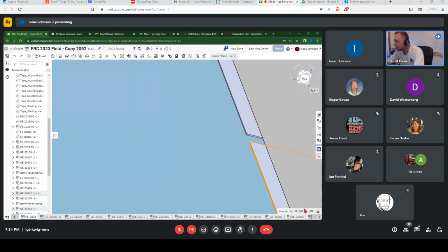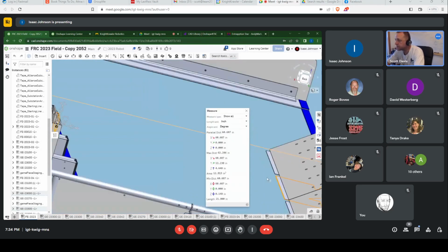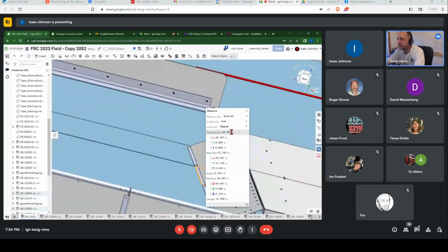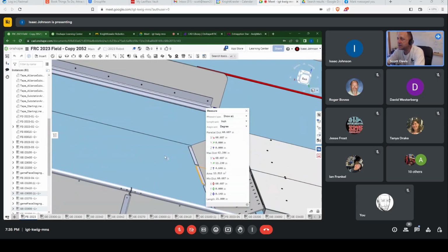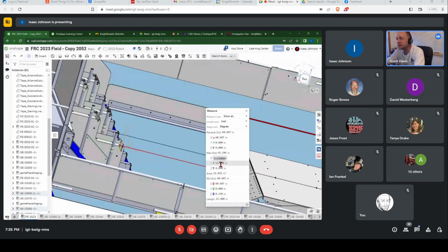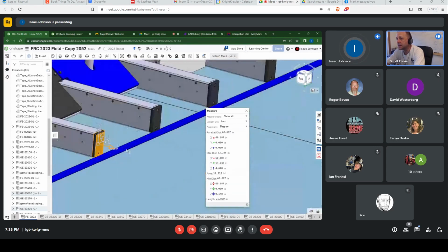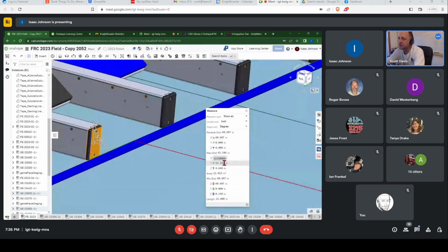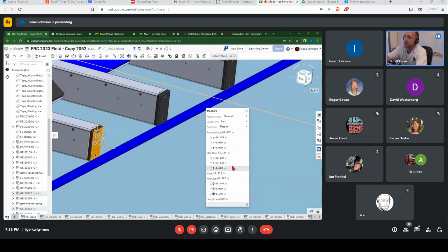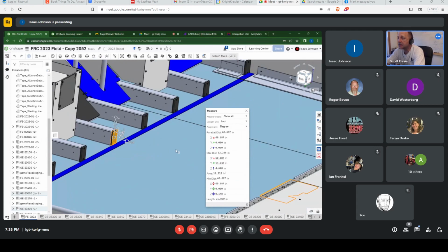And then can you pull up the little tape measure over here? It gives you all kinds of distances. If you hover over them, there's that red line, and see it got highlighted. So 60 and 5/8 is how far it is. And the green line, what's the green line? That's a left and right line. It's just a left and right from where he clicked in the two spots, so you can sort of ignore that. All we really care about is that 60 and 5/8 inches on the X.